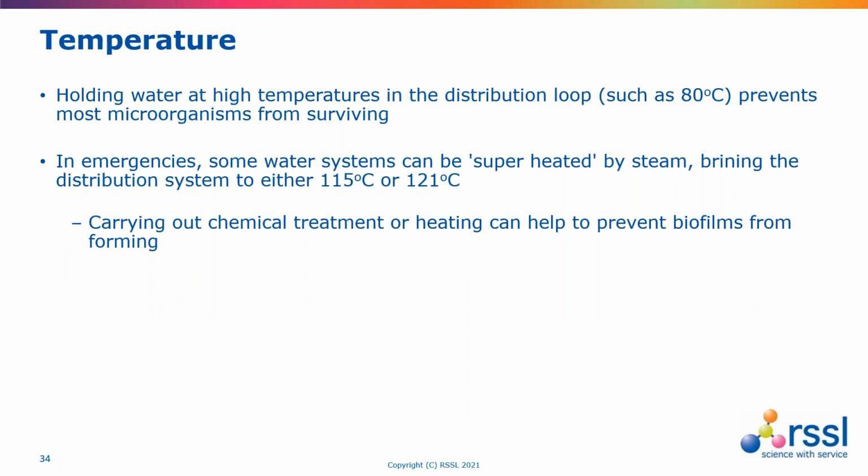With temperature, again, a temperature of 65 degrees and above is very effective, although some choose to run at higher temperatures. But the idea is that the water is continuously circulating at high temperature, therefore it is continuously self-sanitizing. And generally, heat is the most effective control method for keeping contamination in check. Obviously, once a biofilm forms, then it can often be a combination of heat and chemical methods.